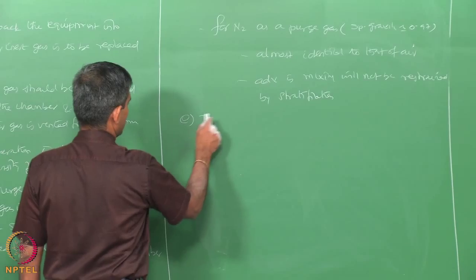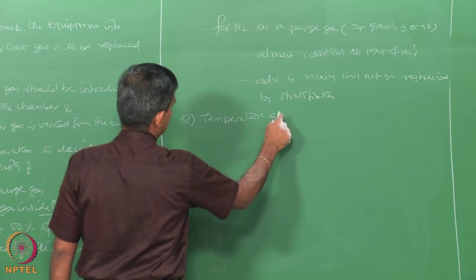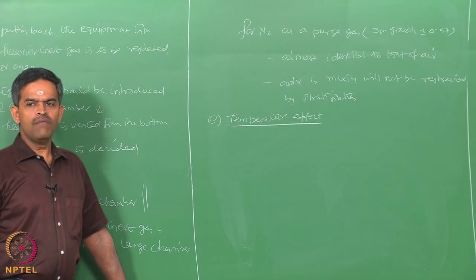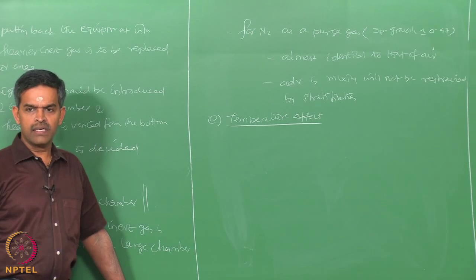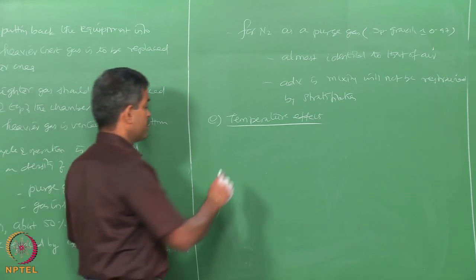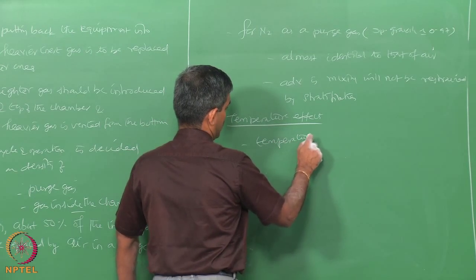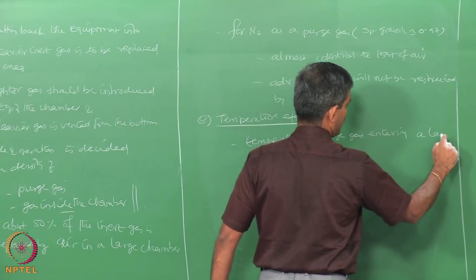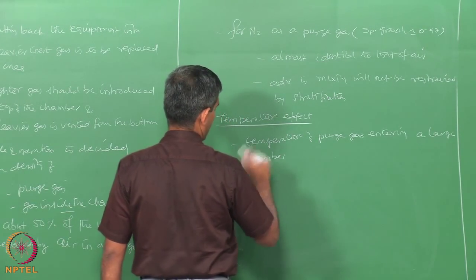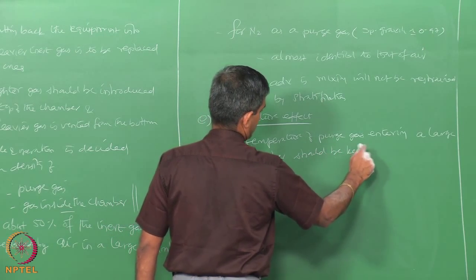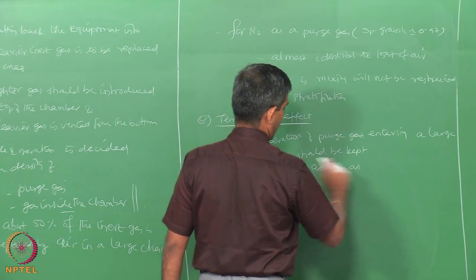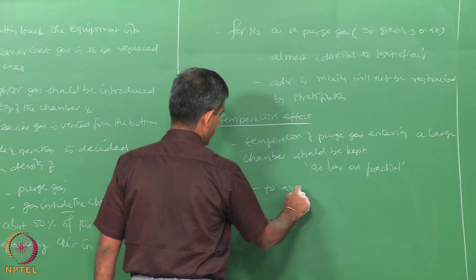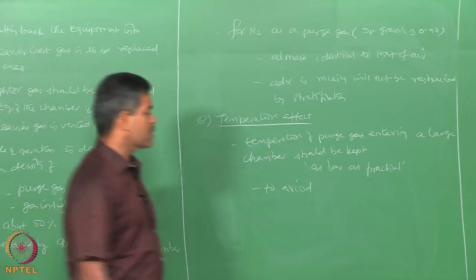The next could be temperature effects. It is always advisable to keep the temperature of the purge gas entering a large chamber as low as practical, to avoid what we call thermal currents.